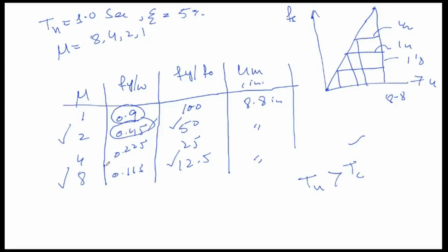But if you are looking at a ductile system like steel frames, you can provide quite large ductility, and this will help you in selecting smaller strength. So you can select any combination for the design, depending on the structural system and the material. But if you select an inadequate combination, for example, you select larger ductility and the system is not ductile, it can have a problem.